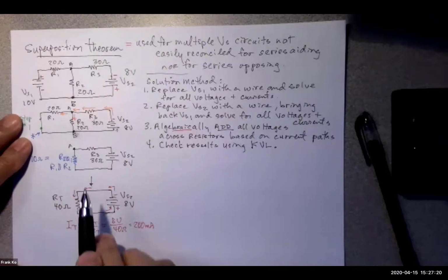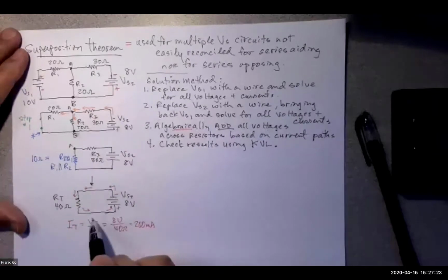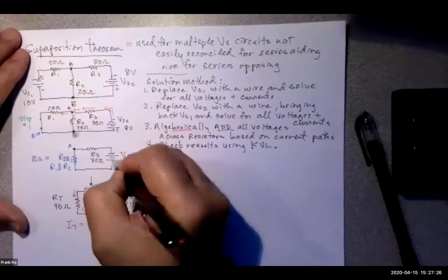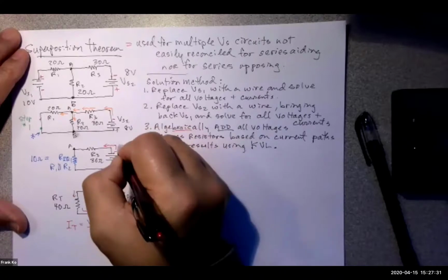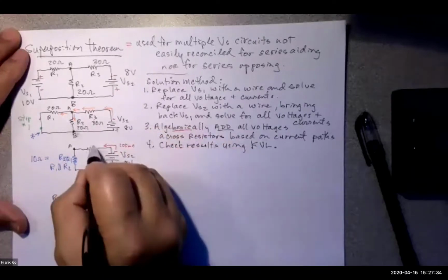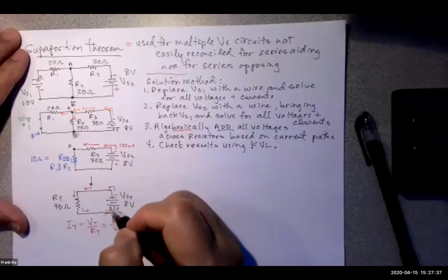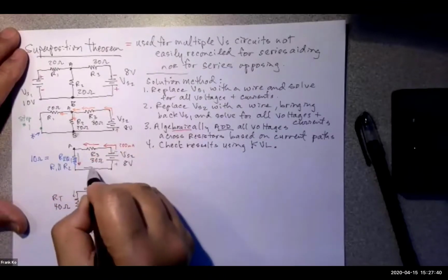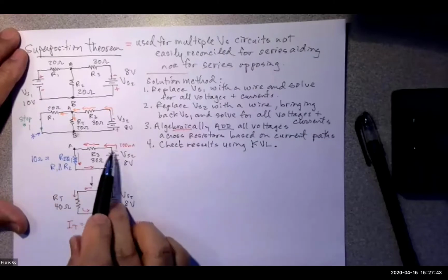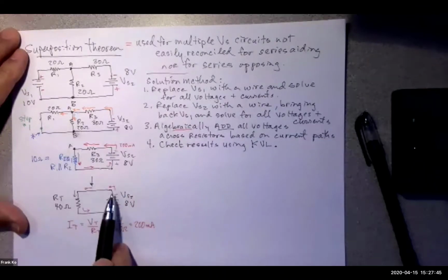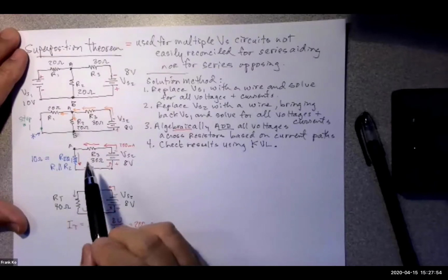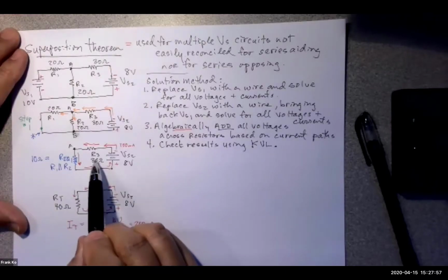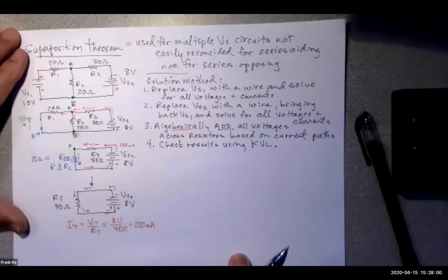Now we have to take this upstairs to this step. If we take the information up here, what can we take? Well, polarities. What else can we take? Direction of current flowing out of the source. That's 200 milliamps right there. And it flows through R3. Ah, interesting. And then it flows down through R1 and back this way and back to the source. Do these arrows match the direction of arrows from my very basic RT circuit? The directions are the same.